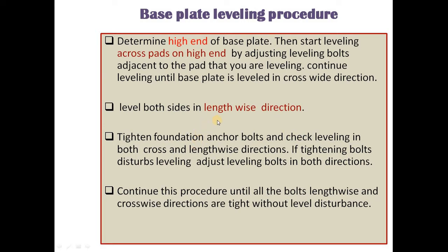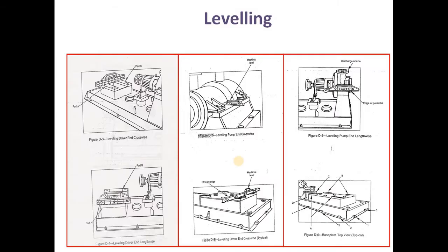In a similar way, like the sole plate, we have to level the base plate crosswise as well as longitudinally. We have to tighten each and every foundation bolt and see the level gauge. If the level is perfect and there is no change in the level, then we can say the base plate leveling is over.